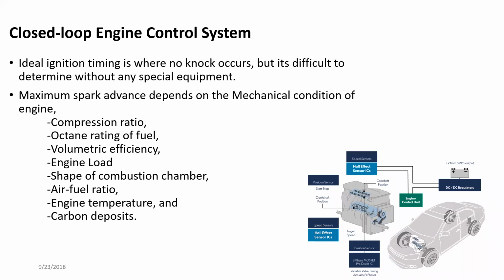How it does this is mainly by considering the knocking of the engine, so it won't let the engine knock. If the engine has started knocking, it will automatically change the ignition timing in order to avoid knocking in the next cycle.